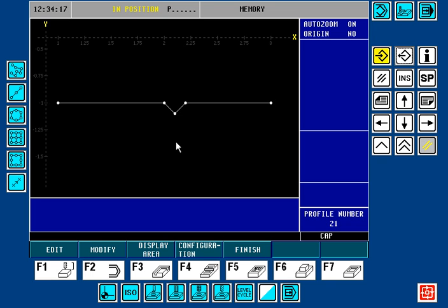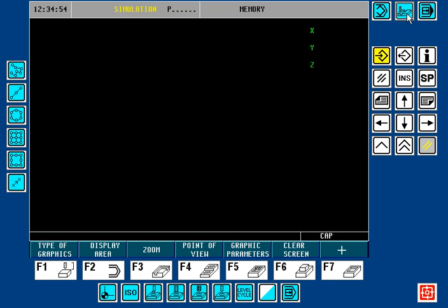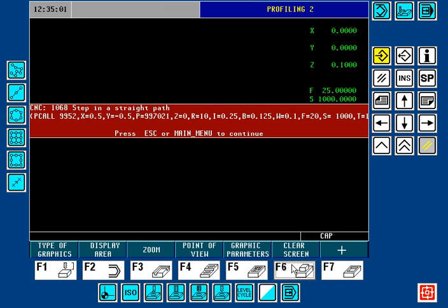And the problem that we're going to see here is that I have a 2-inch cutter. And the 2-inch cutter cannot get down into this small step. So literally the cutter is going to travel over the top of it. But because we have this small step in path, we're going to get an error, basically telling us that the cutter with compensation cannot get in tangent to this line or this line. Let's take a look at this by finishing. Let's go to the graphics simulator. Clear the screen, cycle start, and there we have it.